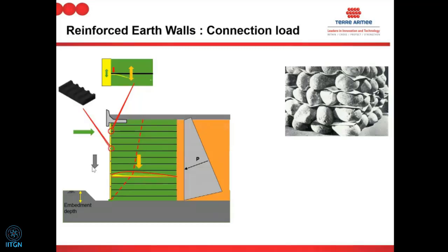And that's why the most important element which is introduced is what we call the bearing pad. The function of the bearing pad is to address the internal compressibility of the reinforced earth field. We generally know that yes, there is a bearing pad, but we don't know the fundamentals of this bearing pad. The fundamental of the bearing pad is purely dependent on the type of soil and the height of the structure. Based on these two elements, the bearing pad is actually decided.